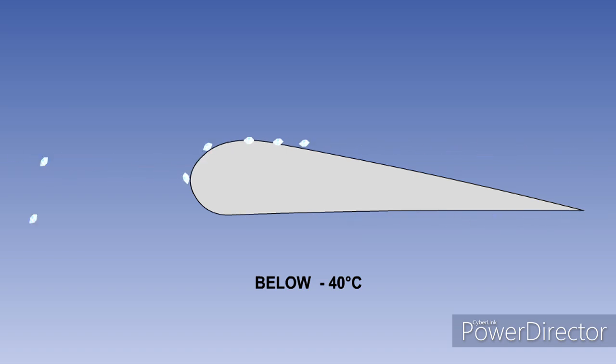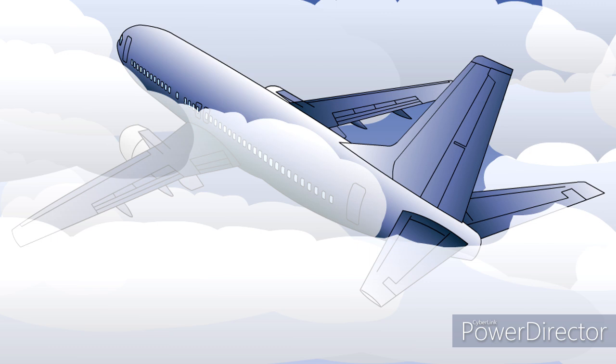The actual amount and shape of the ice buildup depends on the surface temperature and the size of the droplets. A full explanation of icing conditions is given in the Meteorology series of lessons. You should expect ice to be a problem whenever the temperature is between 0 and -40 degrees Celsius, and visible moisture in the form of clouds or rain is present.